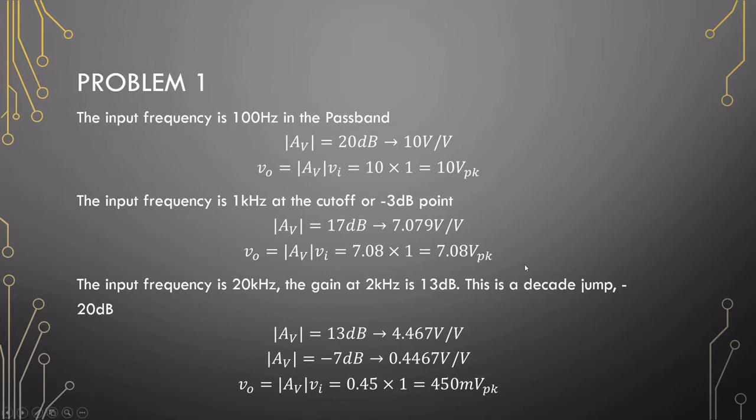Okay, this is also a good way to find the cutoff point for the amplifier. You insert a signal that's known to you and you multiply that by 0.707 and the gain, and you'll find that when your output is at this point right here, if you read off a frequency on your signal generator, that is your cutoff frequency.